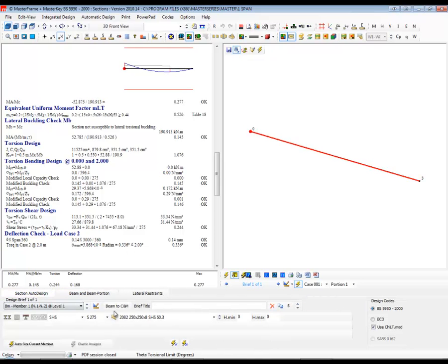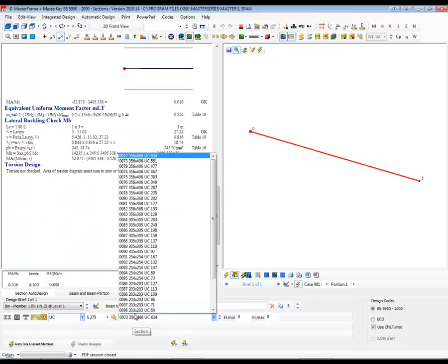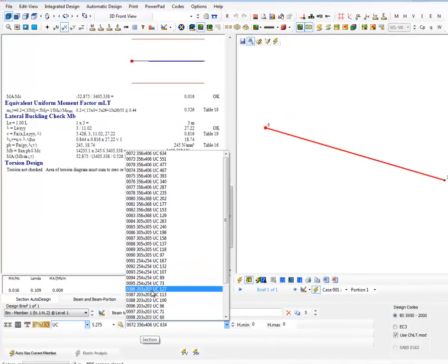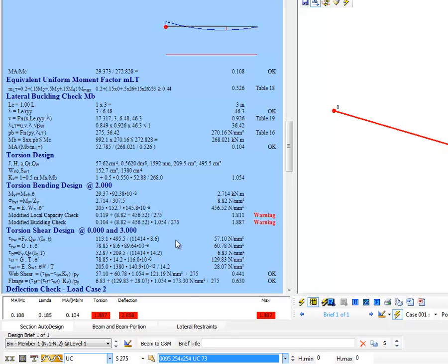If I said, well, instead of a 250 by 250 by 8, which is 60 kilograms, if I put in a 254 UC, what would happen? And I always enjoy doing this because it's around that weight, and you can see similar weight, but we're failing miserably on torsion and deflections.